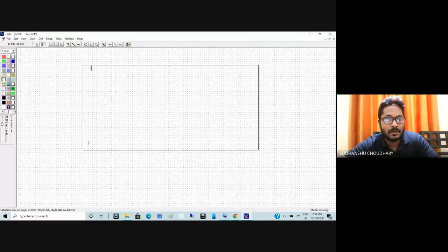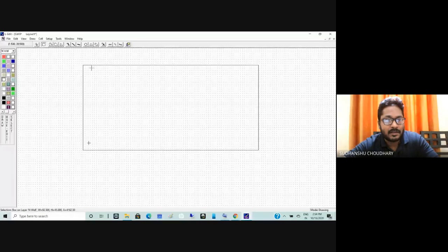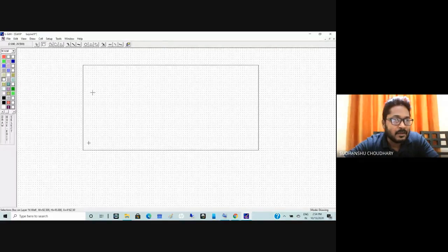So first of all, you will draw the layout on the paper by considering minimum possible dimension, and then come on to this window on layout editor to draw the final layout, because then only your transistor will be an optimum, efficient transistor. The transistor which I am drawing is just an arbitrary transistor, so it may not be very efficient. Okay, so N-well I have drawn.